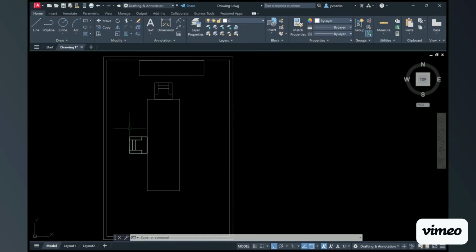Now we're going to copy this chair on both sides to the left and right. In doing that, I'm going to select copy after I've grabbed the object. Specify the base point. I'm just going to go to the outside arm of the chair and move my mouse over. I want to array this, which means I'm going to copy it perfectly perpendicular, typing in the letter A. I want to array this twice, so the number of items is going to be 2. Press enter, and it's asking me to specify the point or that distance that I'm looking for.